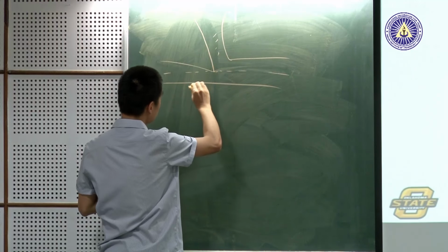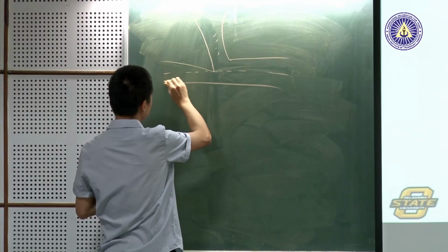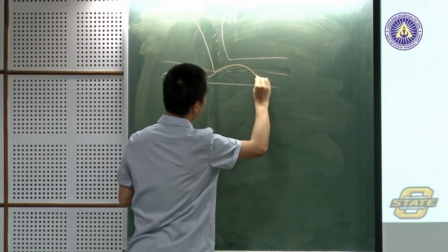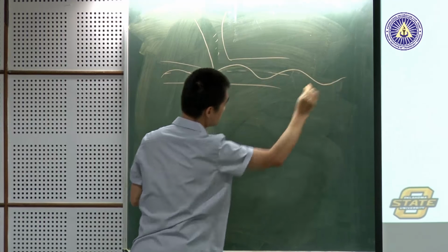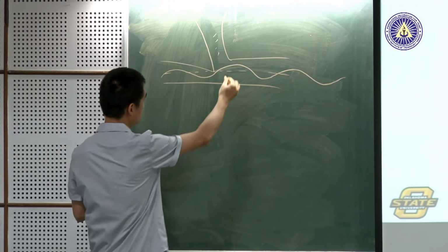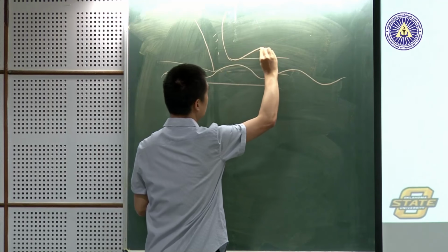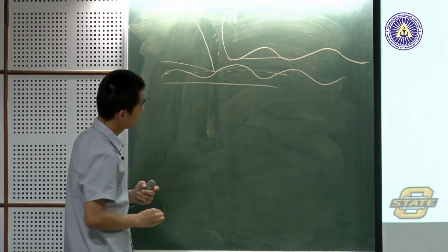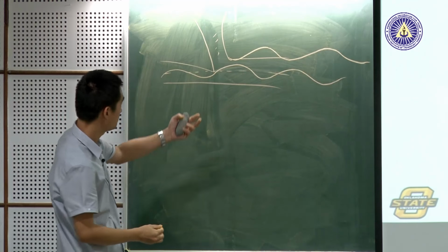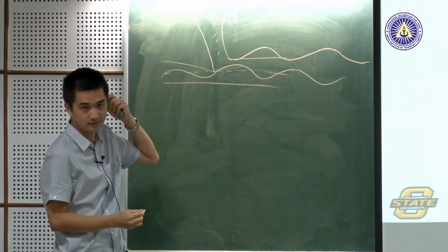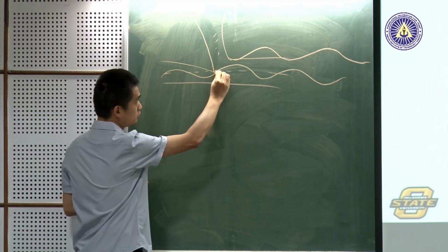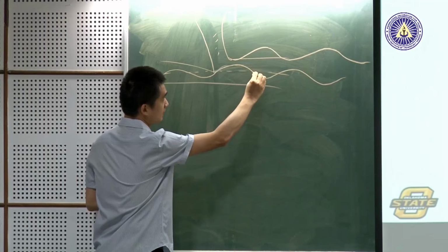If it leaves waviness here, that is the current wave, and this is the previous wave. When chatter happens, those two are not in phase, which is illustrated here. So this edge moves to here, back to here.